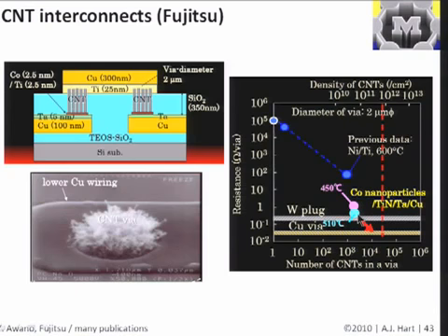If you grow nanotubes with a lower defect density, their electrical conductivity is higher because you have less scattering due to defects and flaws in the walls, due to this diffusive transport. So there is a direct relation between the characteristics of nanotube transport in that diffusive regime and their electrical properties. For me, this is one of the biggest manufacturing challenges and examples where nanotubes could make a practical difference.